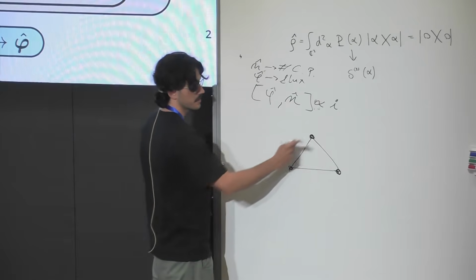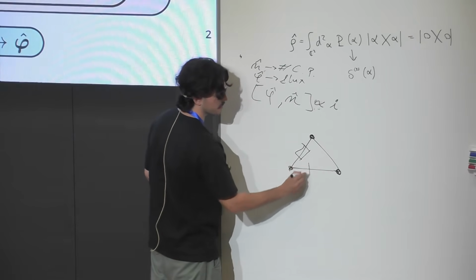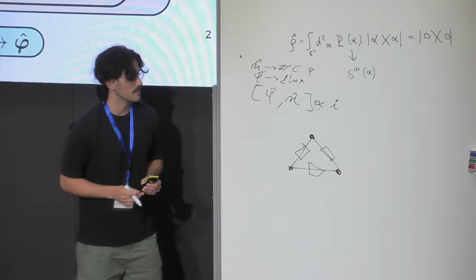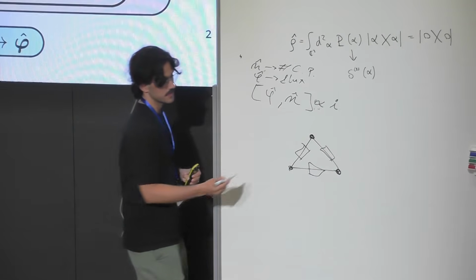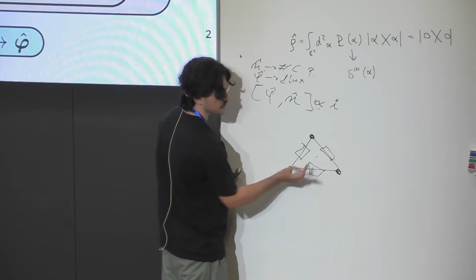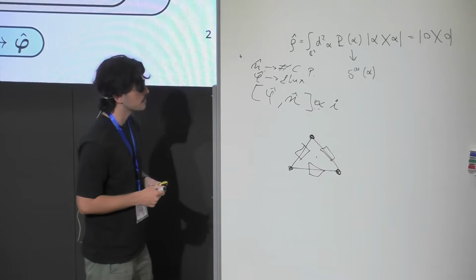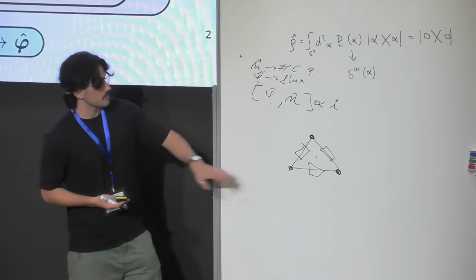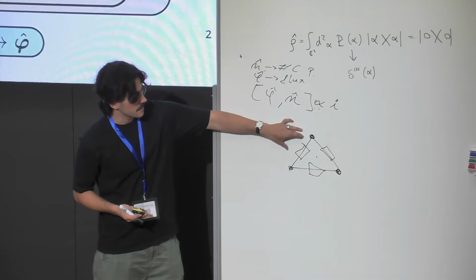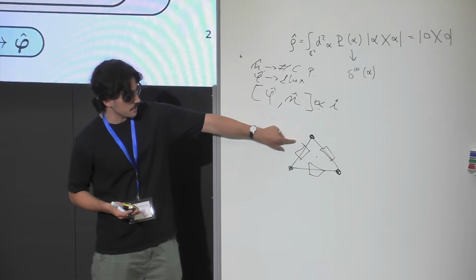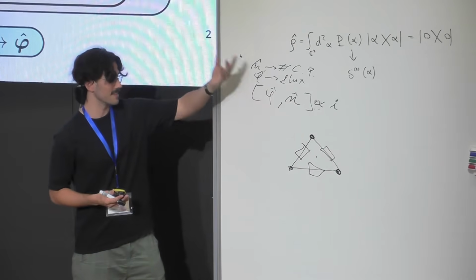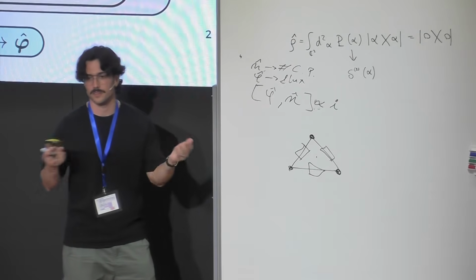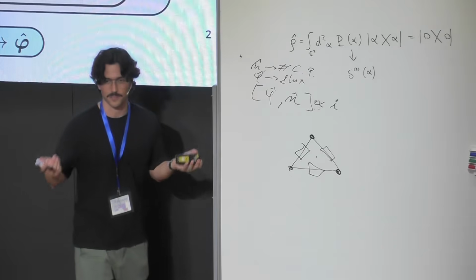The nodes are where the elements are being connected. And the flux is basically the magnetic flux that's going through the system, right? So if you take this, then make a matrix with the different elements, put that matrix in the Hamiltonian and apply this quantization, then you get your quantized superconducting circuit.